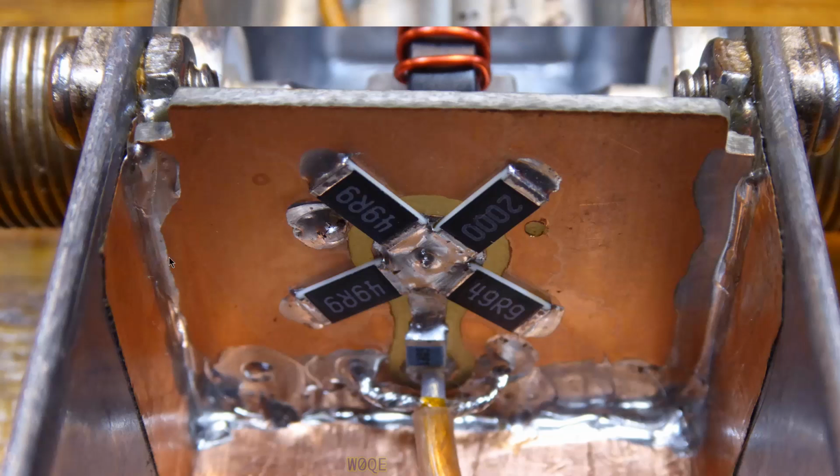This is just a piece of single-sided printed circuit board, which I've taken a Dremel tool and ground out like this dog bone shape, and it's ground out here too. It's ground out down here also, so that I have two pads on there. I have a pad down here where the center connector of the output coax connects, and here's a connection to ground on both, two short paths.